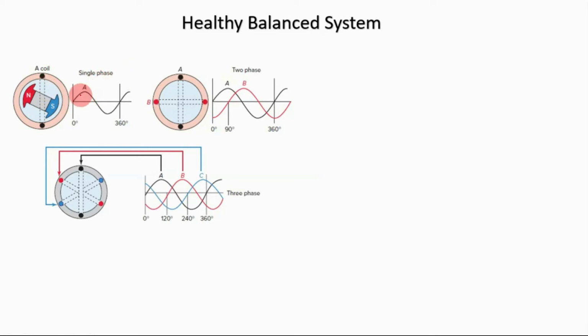So if your coil is subject to the magnetic flux of the north here, for instance, and this is the south, the coil is at maximum value. The induced voltage the coil is taking here is at maximum. When it moves, it goes down to the horizontal position. This is now your north and this is your south of the magnet, and since it is in horizontal position, there is no cutting of flux here, so the voltage will be 0.